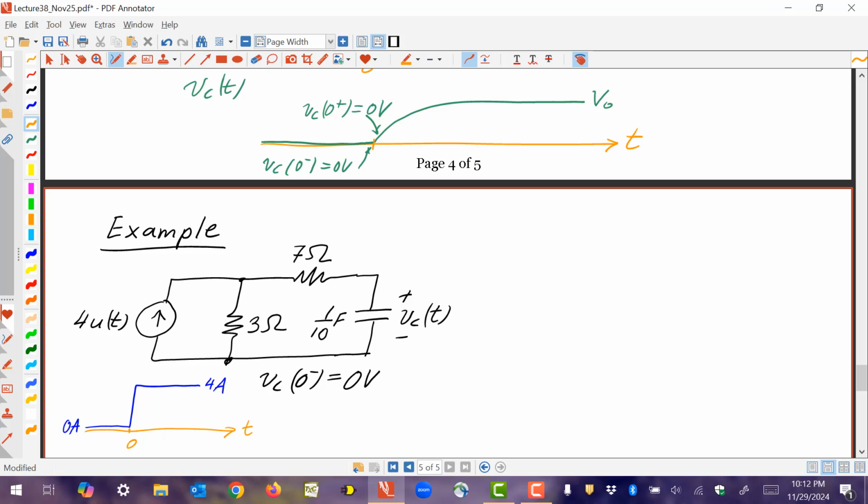Okay. Now again, we can simplify first, then take Laplace transform, simplify. But the important thing is that whenever you can, you should try to simplify at some point before you start to fully analyze a circuit. So let's take the Laplace transform first. Again, the circuit is going to look very similar, but again, for u(t), this becomes 4 over S amps, current source.